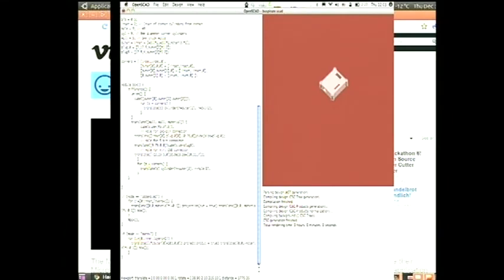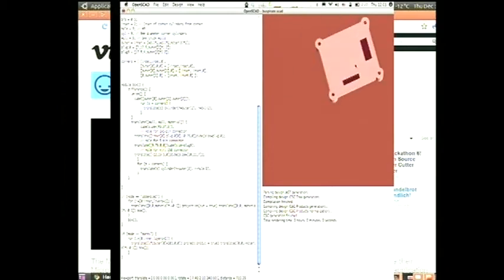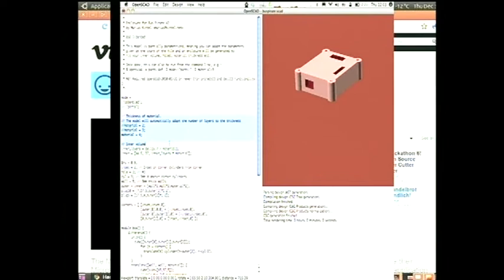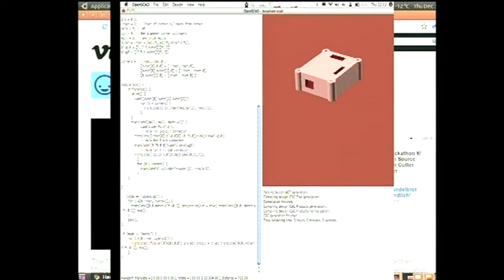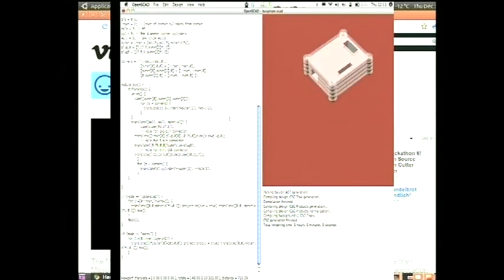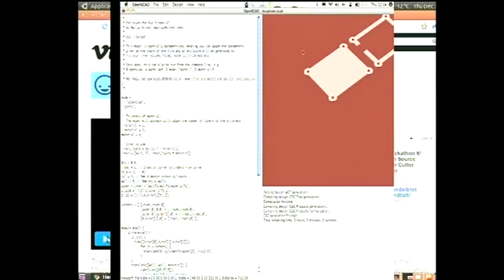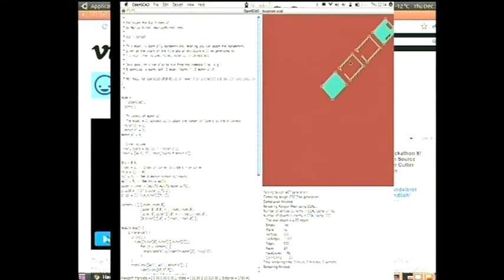Okay, so let's go back here. This is an enclosure for a bus pirate that I modeled a while ago. I want to laser cut this. So I define a material thickness and I slice it automatically because we support slicing, just like this. And I can then, for instance, do an automatic layout for laser cutting. So you can just laser cut the model. It automatically creates the number of slices based on your material thickness.